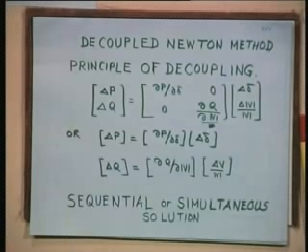This is all about Newton-Raphson. The flow charts have been given in the book for the polar version as well as the rectangular version. As I told you, there is a plus point in polar, there is a plus point in rectangular. Nothing is absolute, it depends on what you want. Let me tell you also one thing, polar is more realistic because it has direct voltage, direct angle.